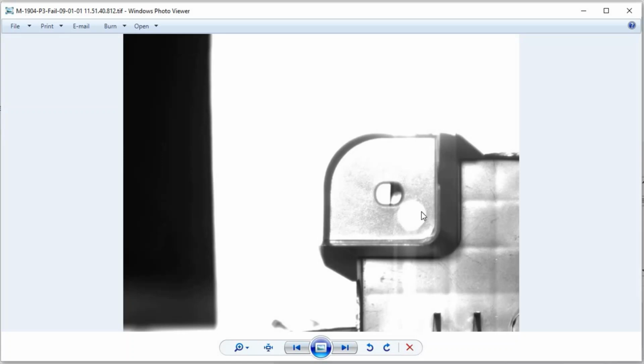Take a look at another picture. This picture isn't too bad. However, in this area, you can see some black dots, or gray dots. They may interfere with the locating methods. Those dark dots may be caused by the wrong direction of the LED light, or the part orientation, either tilted up or down too much.